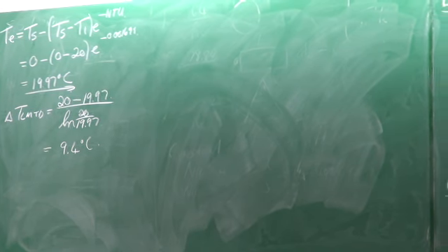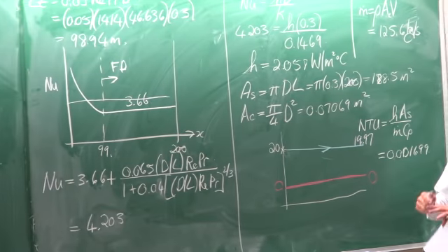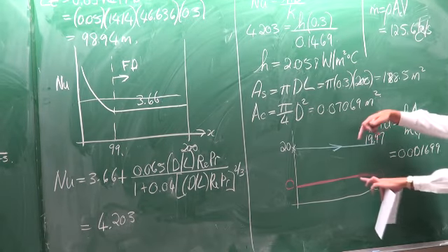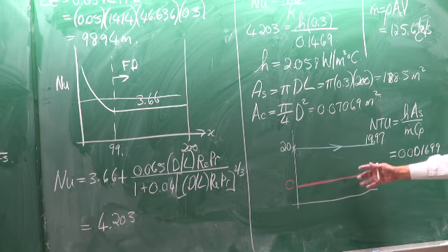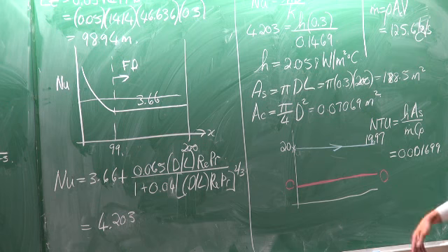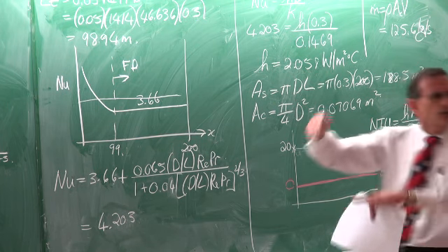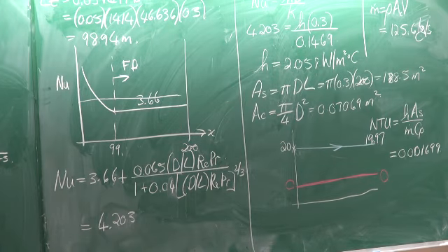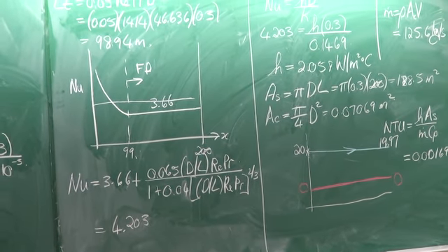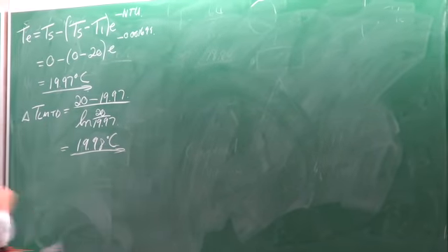That's the advantage of making sketches while you work through it. If you go and calculate the LMTD, what is the LMTD? It is the effective temperature difference between those two streams. It's obviously 20, isn't it? You agree? It's 20 there, it's almost 20 there. Nothing happens. It's a delta T of 20. So if you do a calculation and you get a value like that, then you know your finger was the problem. So it is equal to 19.98. It's 20 degrees Celsius.